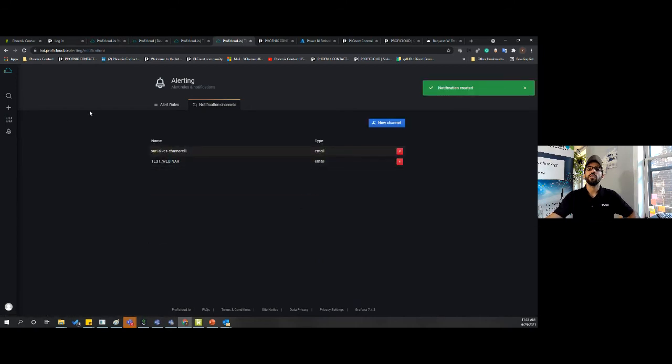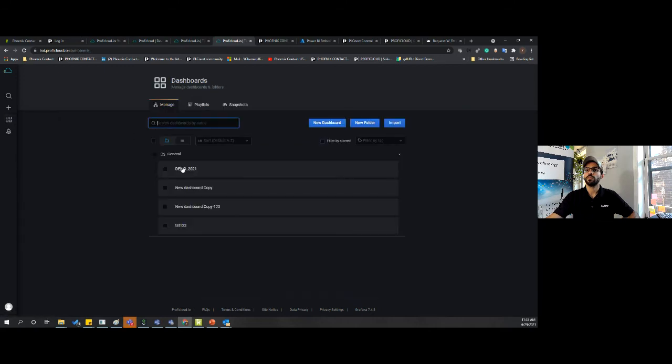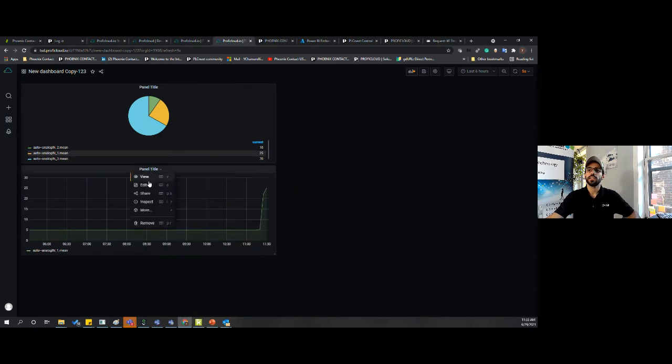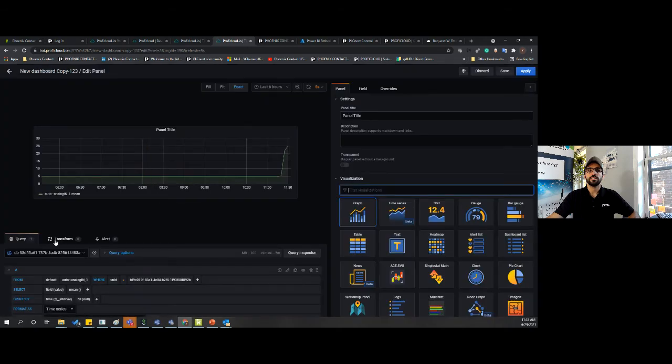Okay. Now back in your dashboard. Going back to this one, Copy 1, 2, 3. Let's say that we want to set an alert for this data point logging in this historian. So you go in, you add it, and then there's a little thing over here called alert.